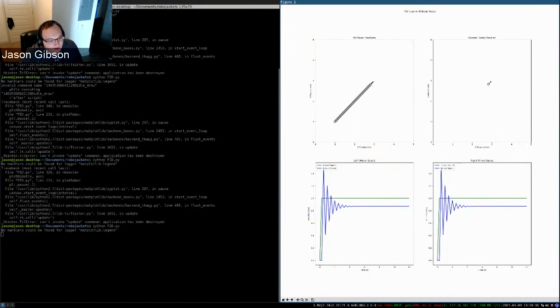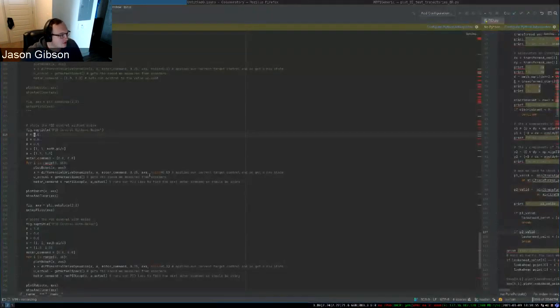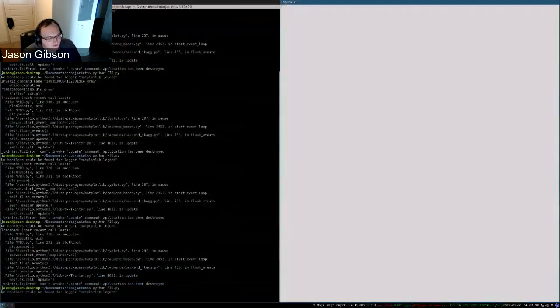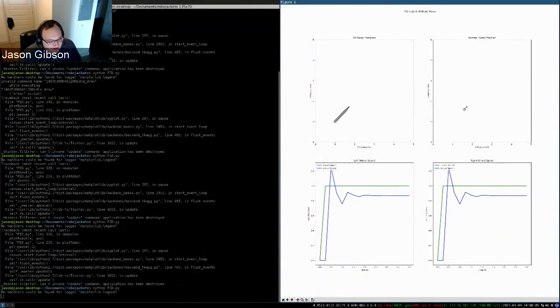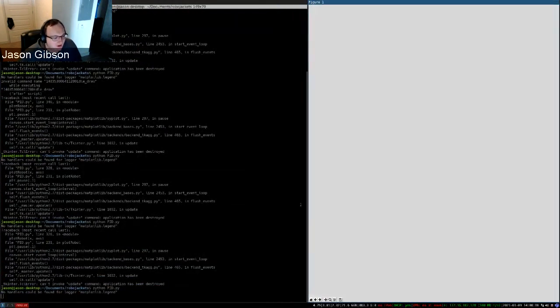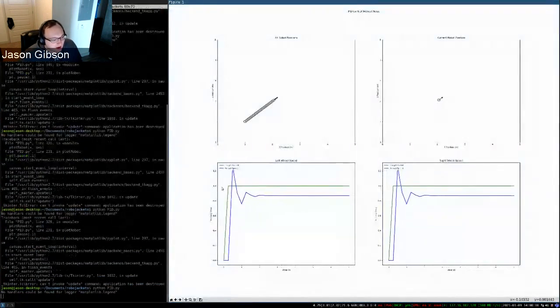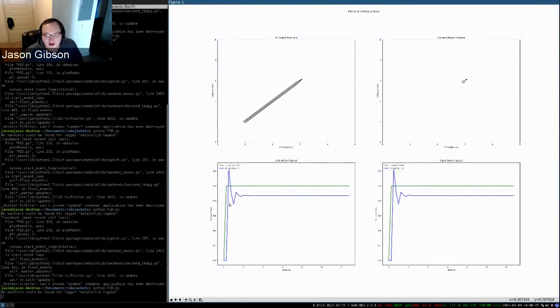And then the next thing you're going to want to do is increase your D. So what you want to do is increase your D to the point where it doesn't overshoot too much. As you can see the difference between when I had no D and a D, before I had this oscillating behavior up here. This one, it oscillated 2 or 3 times, and then it converged to a steady state value. This is what you'd want to see from a decent D.